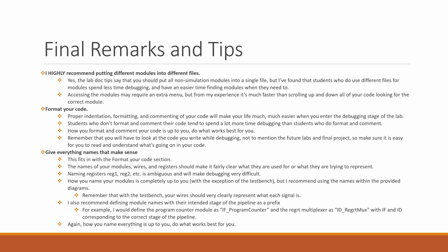My third tip is that you give everything names that make sense. This kind of fits in with the format your code section, but I wanted to make a separate section for this anyways. The names of your modules, wires, and registers should make it very clear what they are used for or what they are trying to represent. If you name registers Reg1, Reg2, etc., this is quite ambiguous and will make your debugging very difficult. How you name your modules is completely up to you, with the exception of the test bench, but I highly recommend that you use the names provided within the diagrams.